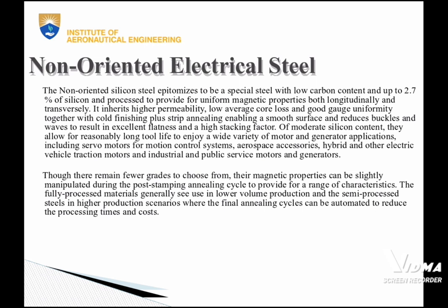It offers higher permeability, low average core losses, and good gauge uniformity, with cold finishing of the strips enabling smooth surfaces and reducing buckles and waves, resulting in excellent flatness and a high stacking factor.